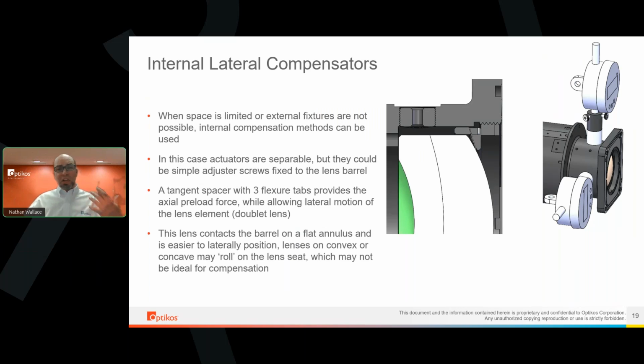And to take this a little bit further, I said earlier that I really like having mechanical feedback, some gauges to say, hey, where did I move this? Where's my zero position? How did I start? There are some port plugs that are in here, and you can thread on these little fixtures that attach the drop gauges. And now I can take my barrel, I need to go compensate it. I can add these little components to them, get my feedback, be able to do my compensation.